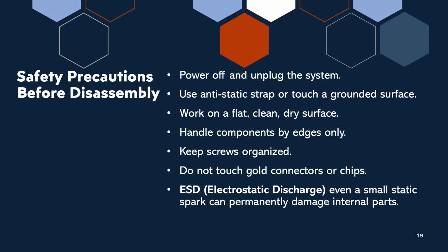Safety precautions before disassembly. Power off and unplug the system. Use an anti-static strap or touch a grounded surface. Work on a flat, clean, dry surface. Handle components by the edges only. Keep screws organized. Do not touch gold connectors or chips. Electrostatic discharge: even a small static spark can permanently damage internal parts, so be careful of that.